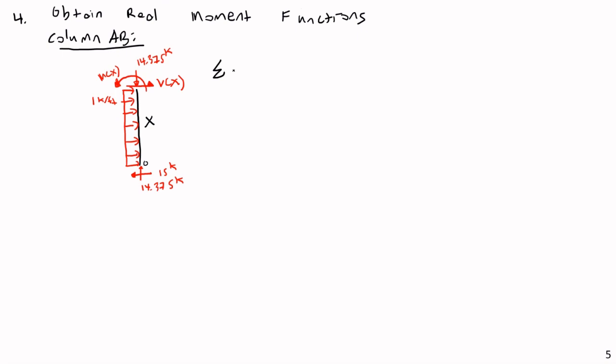You can if you want, but ultimately my goal is not to solve for every single shear and moment function in this frame. All I really need is the moment function, so why even bother getting v of x? I mean, I could, but this example is long enough as is. So let's do a sum of moments about point x.